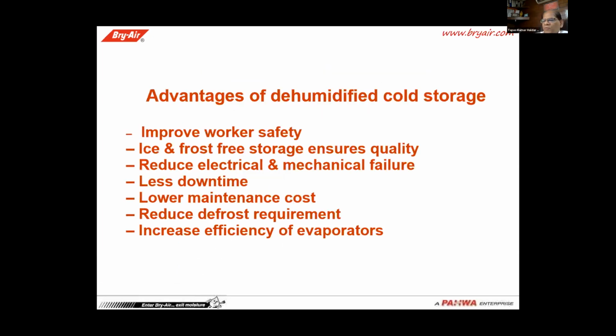And we supply dehumidifiers to the cold storage. What happened? It improved worker safety. That means if there is no ice, what will happen? People can work properly. Ice- and frost-free storage ensures quality of the product because there is no damage to the product itself. It reduces electrical and mechanical failure, because if there is ice on these, there will be a problem